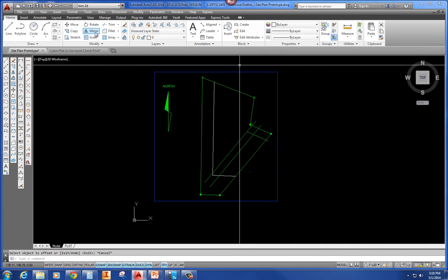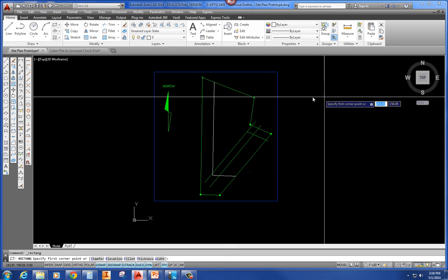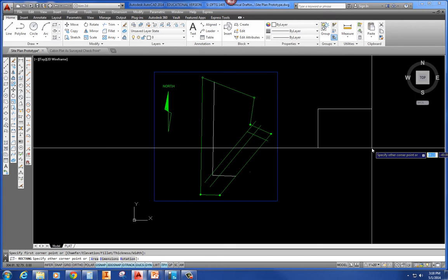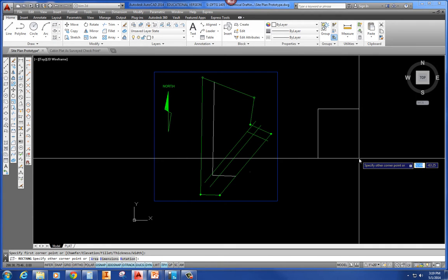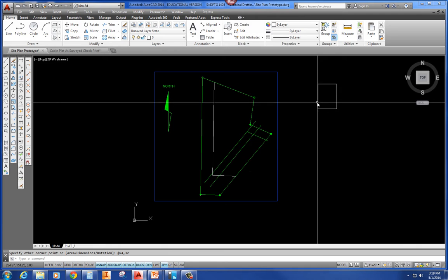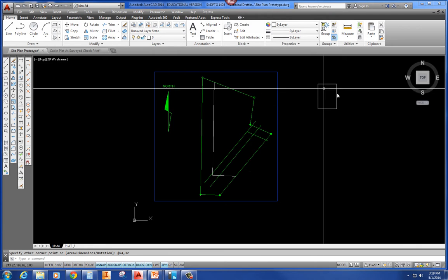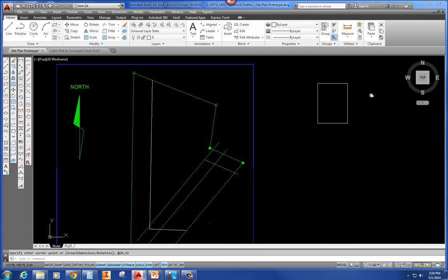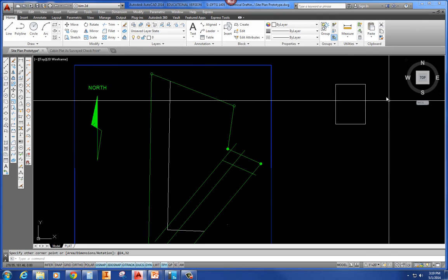Now I'm going to draw a house. I'm just going to draw a box. And you're going to draw it in rectangular format, and then you're going to move it in, then you're going to have to line it. So it's going to start at any corner. And we see that the house is 24 foot wide, comma, 32 foot long with a porch. And there's the size of your house. So you'll draw that little porch here, and then you'll put the text on there, or you can copy your house and put it in here if you want to.